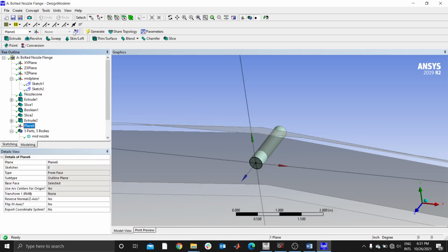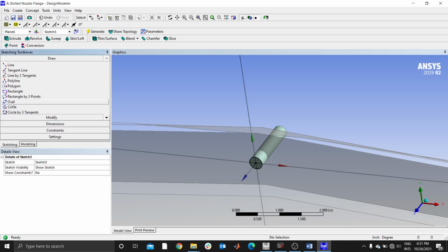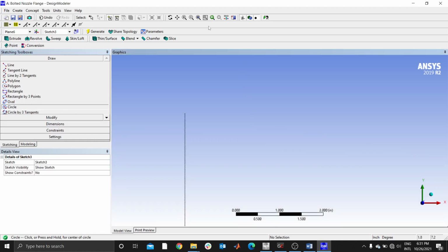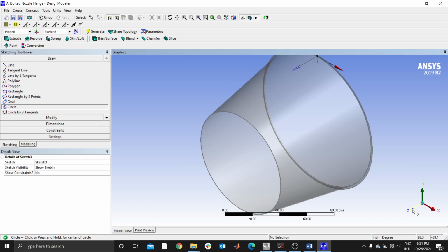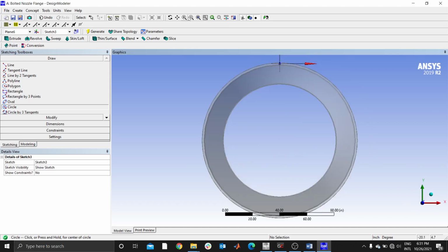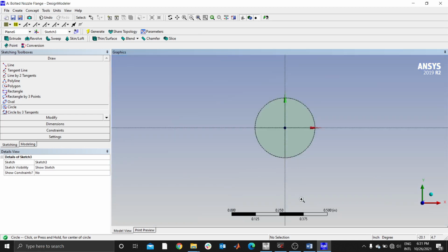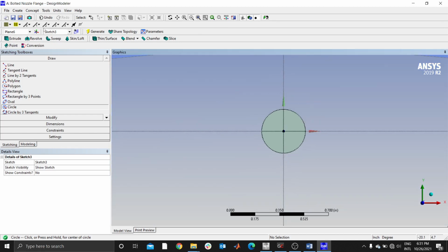Now the plane, sketch, go to sketching, circle. Before you go to sketch, let me show you another method. If it is isometric here, you can just click the Z axis to be normal to the sketch plane. Therefore, we need a circle here. Please select circle again. We need one circle and another one. Make sure this T icon is indicated to represent tangency.